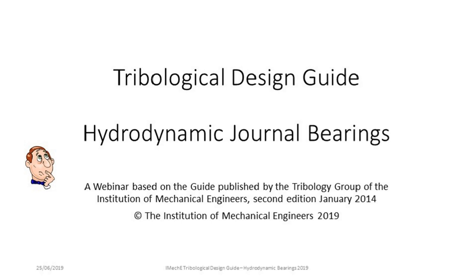In hybrid vehicles, the cost is in the electrical supply. So the engine of hybrid vehicles, this is something that came out in the various talks, is likely to get simpler rather than more complicated. Because the engine can run at its sweet spot more continuously, it doesn't have to have such a broad band of operation.